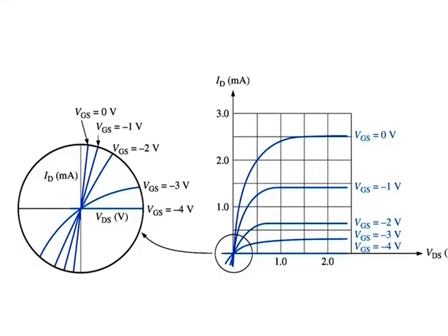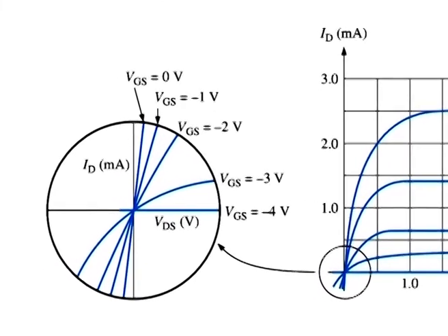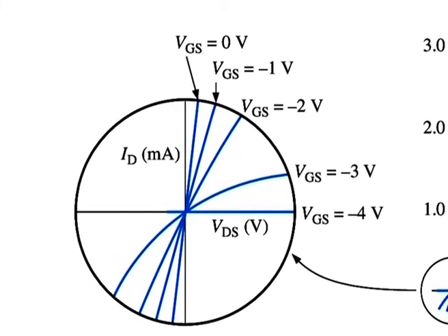As you learned earlier, transconductance is defined as a change in drain current for a given change in gate to source voltage. So, the key factor when you bias at the origin is the transconductance. This figure shows the characteristic curves expanded at the origin. Notice that the ohmic regions extend in the third quadrant.